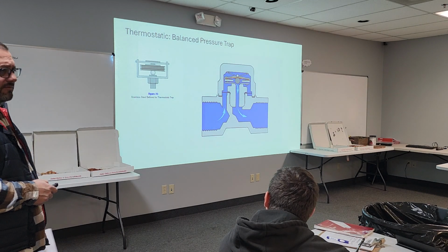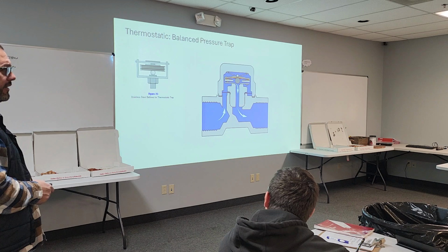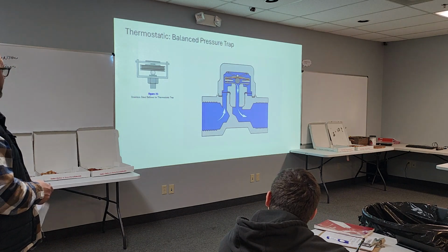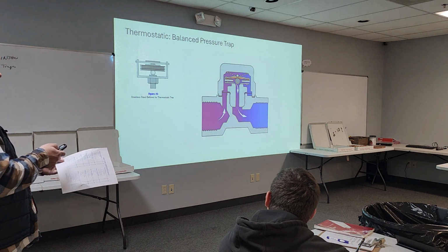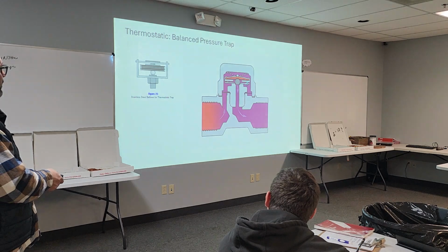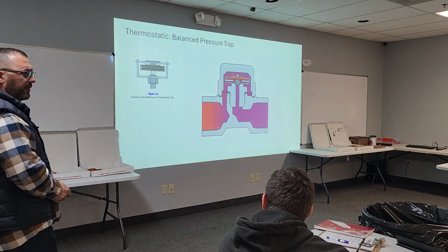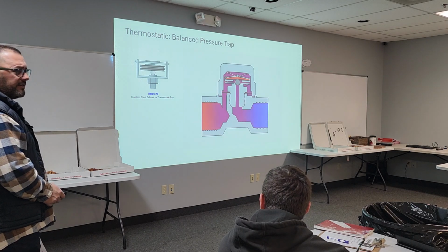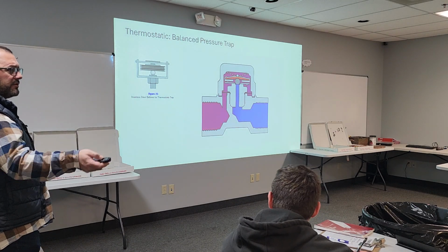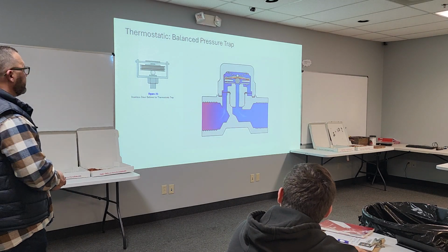Passes air like nobody's business. Great air vents. Passes condensate. When it heats up, that alcohol water fill expands and closes off that head and seat. Don't see a lot of them. Pharmaceuticals, see them more as air vents than anything. Pharmaceuticals, food plants, and some sterilizers.